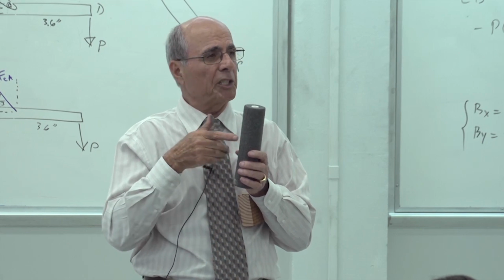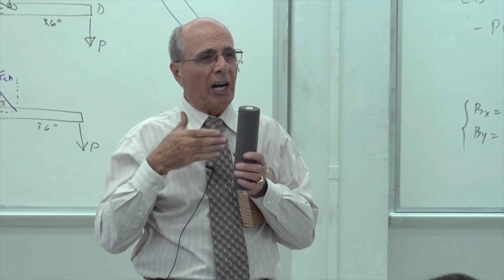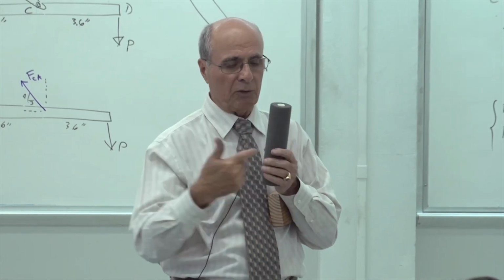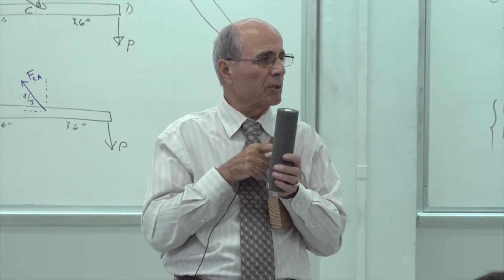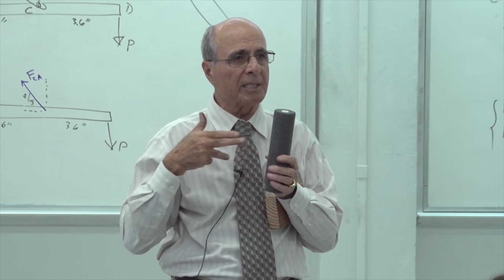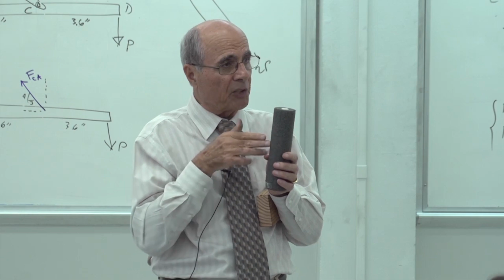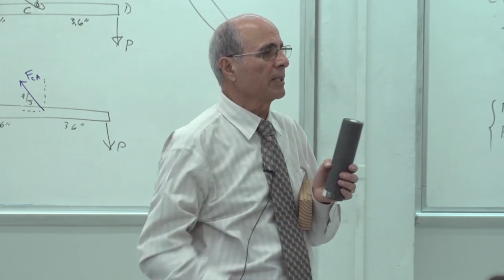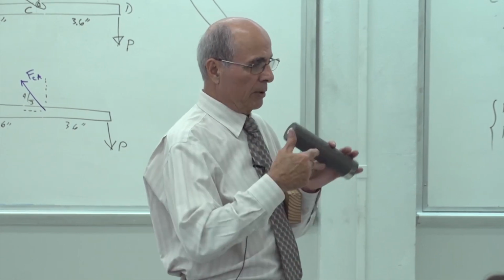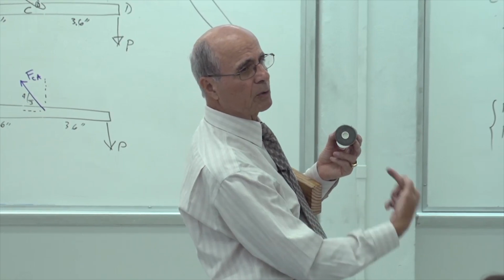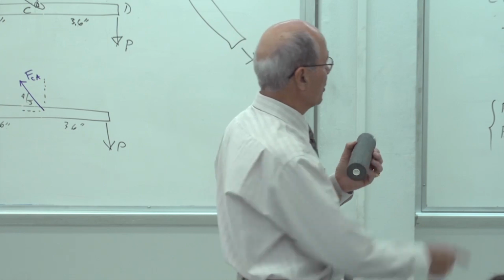So obviously the shear is going to be under the resultant of these two forces, because this is round, so you have a force here and a force here. Is that understood? Because the shear-off is at the resultant of these two forces, it is going to shear off like that. The pin is sitting like that, but there is a force here and a force here, so you have to find the resultant. So that's what we are doing.